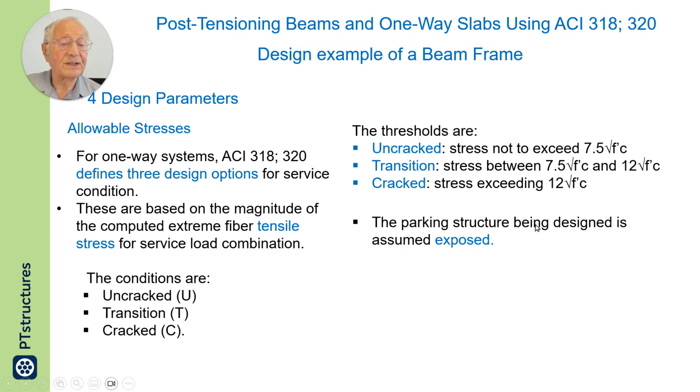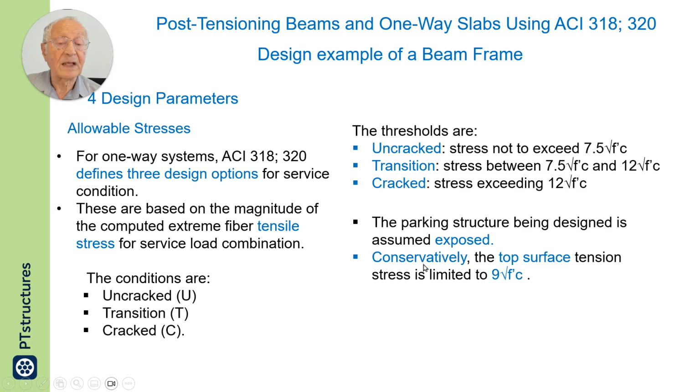The parking structure is assumed to be in an exposed area because that again determines the allowable stresses. Exposed area, by exposed area, open to air. Conservatively, the top surface is limited to 9 square root f prime c. We, as designer, determine what is the stress we target. I have targeted, in this example, 9 square root.